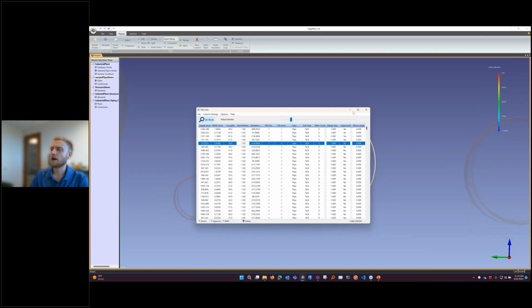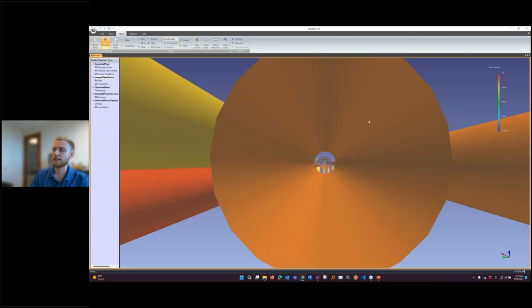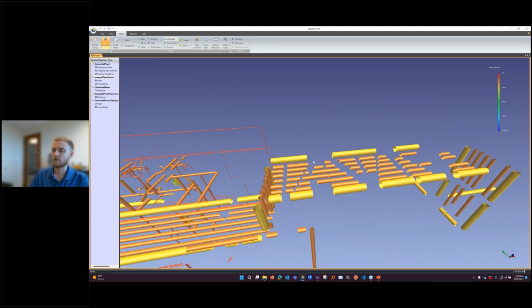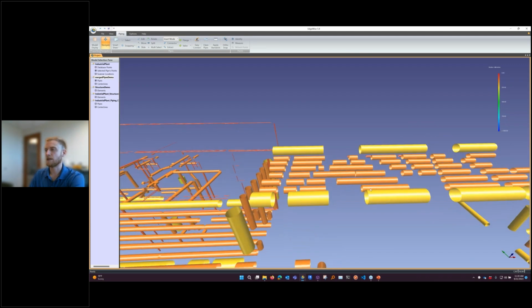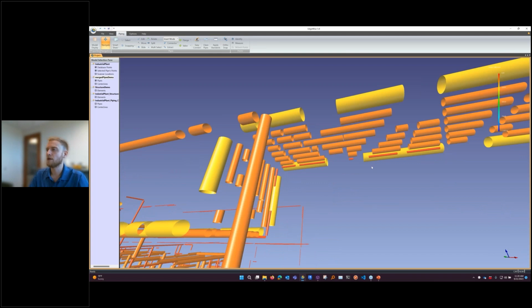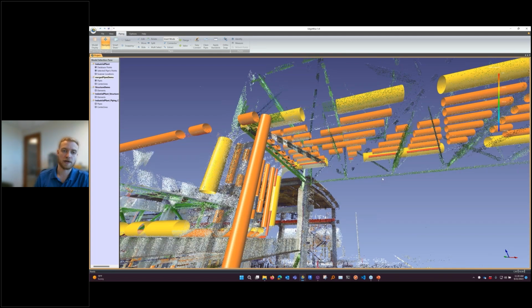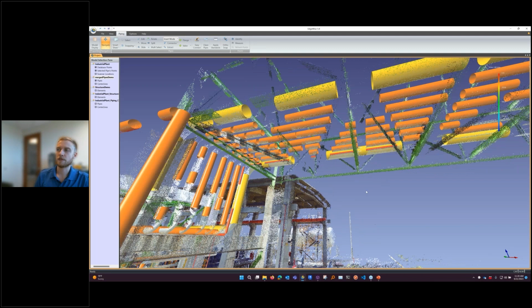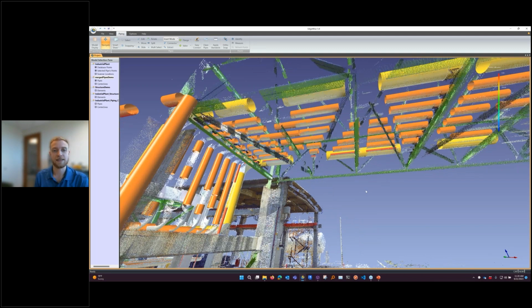So once we've got our QA process completed, then we need to go through and start filling in all of these gaps that are in the software. And this is extremely common because of shadows in the point cloud. So this is one of the holes in scanning, is that there's almost always gaps and shadows and holes in the point cloud. And this is something that we can account for very well in general, because the next tool we have is going to try and automatically fill in those gaps. But this is part of the workflow. We need to fill those in.